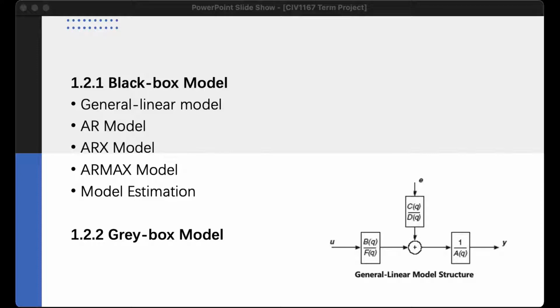Transfer function models can describe both continuous time and discrete time systems. Use the transfer function model structure to represent single input and single output physical systems, or multiple input and single output physical systems. For more complicated multiple input and multiple output physical systems, use the state space model structure.